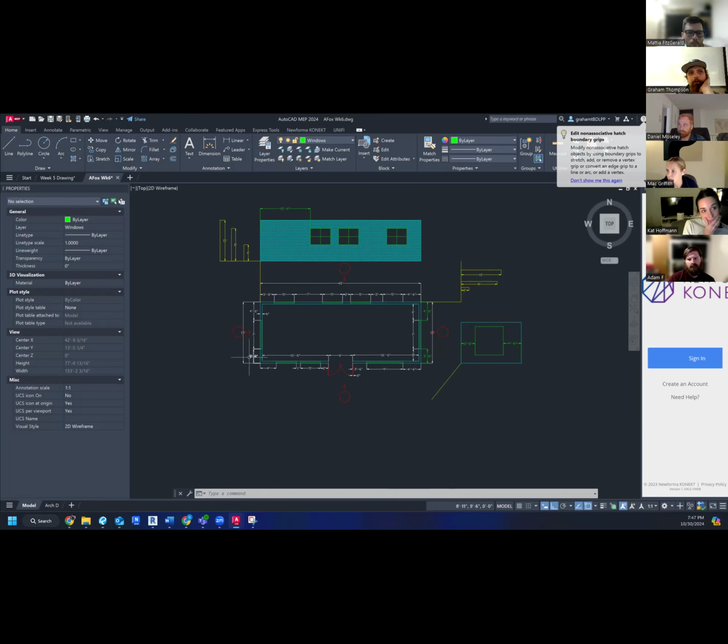Again, same concept with these ones. Your story pole is going to be upside down, so just think about how you want to draw that. If you wanted to draw it from this bottom left and make it right side up, you can. The problem is you can't utilize those windows to transfer that line down until you mirror that. If you just did that and then mirrored it and flipped it, you'd be good to go.